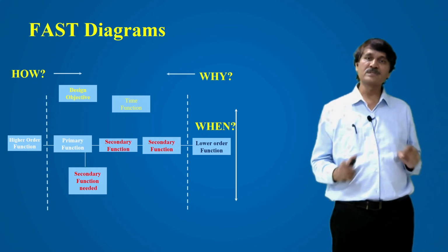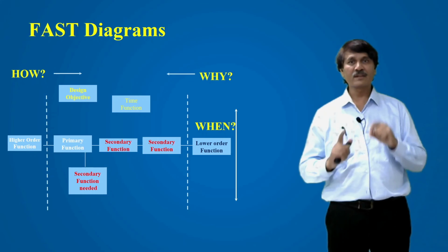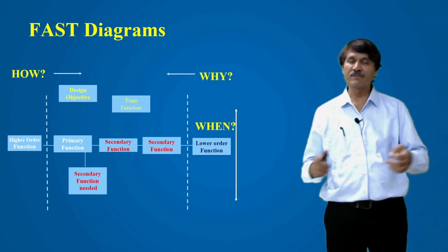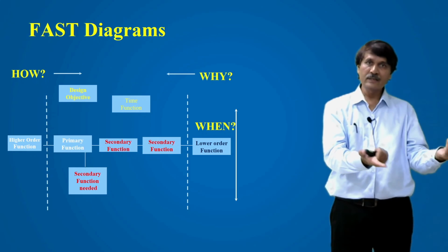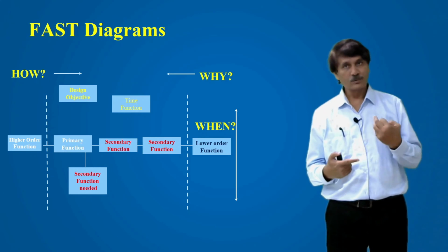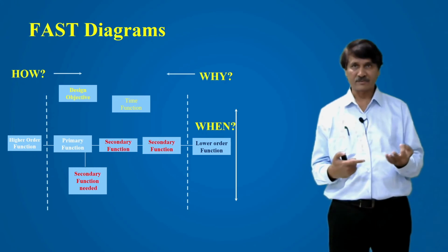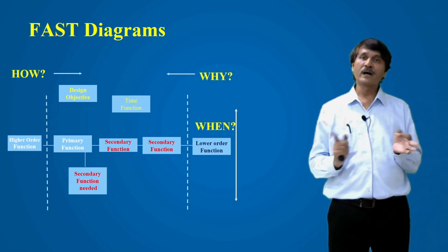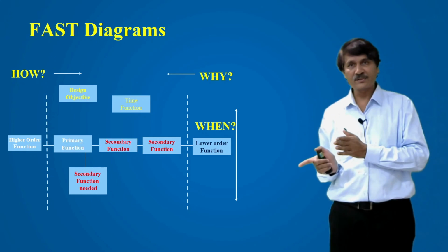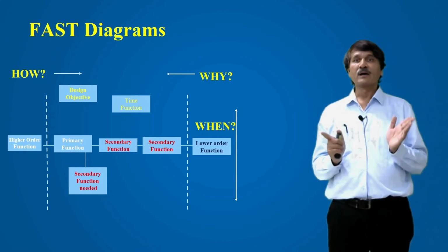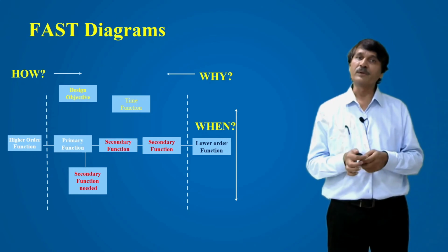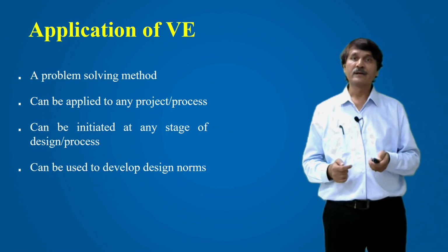In the case of a phone, just as I have said, the basic function is related to calls, etc. You have added a calendar, you have added a stopwatch, you have added say an alarm. Many things you have added in that. So these are going to be the secondary functions. So based on this, you are going to analyze the product, you are going to categorize what the different primary functions are, what the secondary functions are, and on the basis of that, with this FAST diagram, the product is going to be defined and going to be designed.